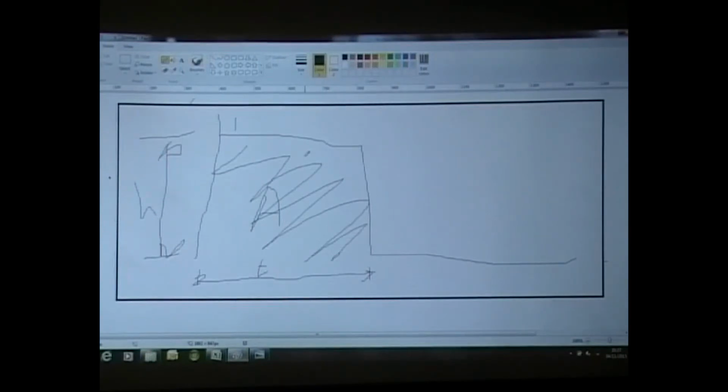So we get a chunk of light. What's the problem with that? It's not the intensity, that's just kind of an averagey figure. We'll get back to that. We can work out the intensity from it. The problem is, it only works if these are nice rectangular pulses. That's the only way it works. Now, fortunately, that's exactly what LEDs are. LEDs turn on and turn off so fast, you can effectively consider these to be vertical.